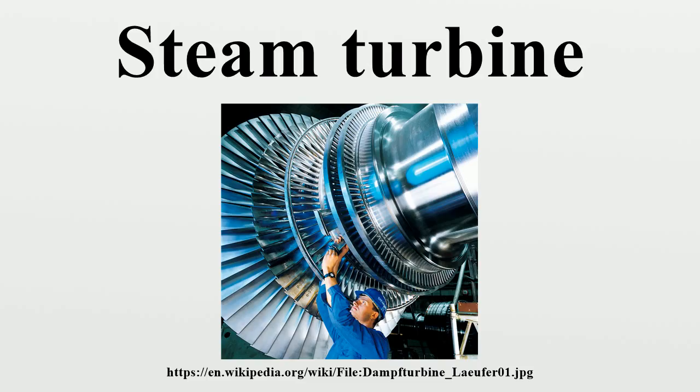Steam supply and exhaust conditions. These types include condensing, non-condensing, reheat, extraction and induction. Condensing turbines are most commonly found in electrical power plants. These turbines receive steam from a boiler and exhaust it to a condenser. The exhausted steam is at a pressure well below atmospheric, and is in a partially condensed state, typically of a quality near 90%.